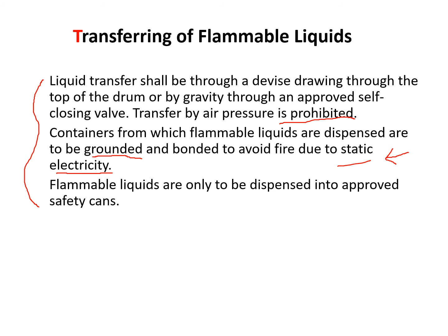So flammable liquids can only be poured, dispensed or transferred into safety cans. These are special cans. We cannot use normal cans to carry flammable liquids. For example, we cannot use empty water bottles or empty soda bottles. Those are not actually safety cans.